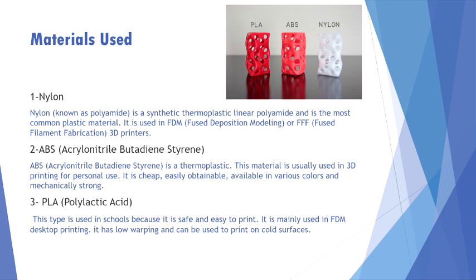First, we have nylon. Nylon is a synthetic thermoplastic. It's commonly used in FDM and FFF 3D printing. Nylon is a tough and semi-flexible material that offers high impact and abrasion resistance. It is an ideal choice for printing durable parts.